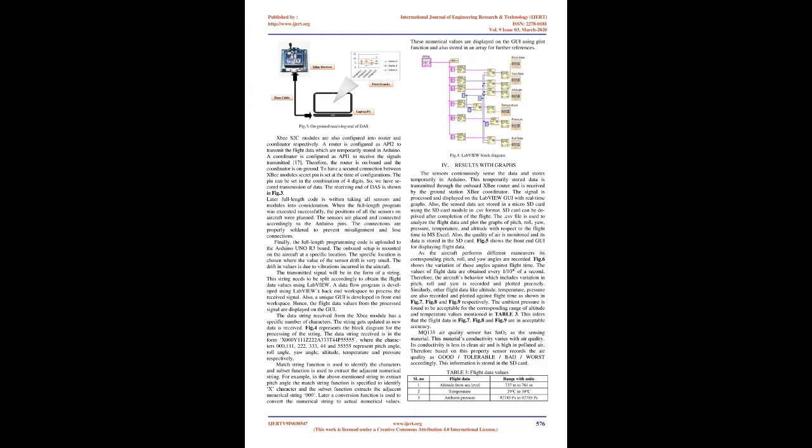Gyroscope/accelerometer sensor: the MPU 6050 triple axis accelerometer and gyro is used for sensing aircraft pitch and roll angles. It has a standard I2C interface with gyroscopic range ±250, ±500, ±1000, ±2000 degrees/second and accelerometer range ±2G, ±4G, ±8G, ±16G.